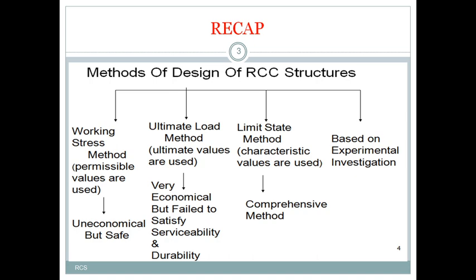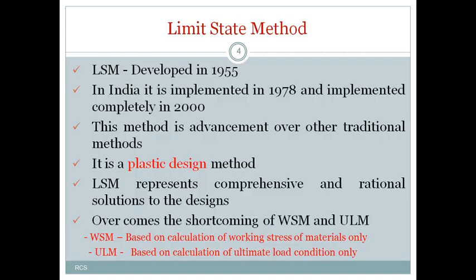Then to overcome the drawbacks of these two methods, the working stress method and the ultimate load method, one more method was developed, that is the limit state method. This method is based on characteristic values, and it is a comprehensive method. That means it can take the working loads as well as ultimate loads for designing RC structures. Now in this class we are going to discuss in detail this limit state method.